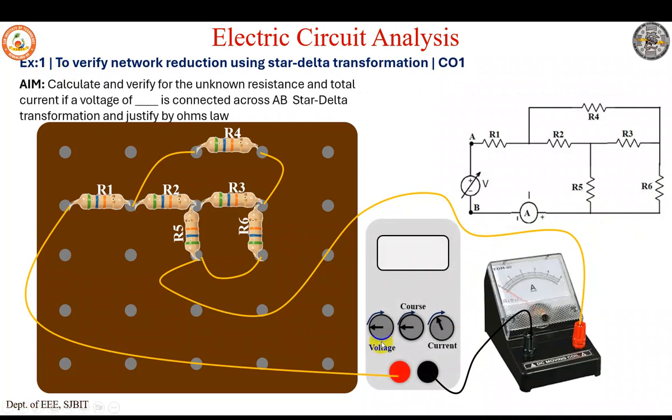Now, as discussed, set the current maximum, and set the voltage. As I told, the maximum voltage you can set is 30, and with a slight increase using voltage coarse it will go up to 32 volts. But the panel, the nameplate detail, says it is 0 to 30 volts. With voltage coarse, you can increase it up to an extra 2 volts. So using voltage coarse, and the voltage value, let us assume that it is set to 25 volts.